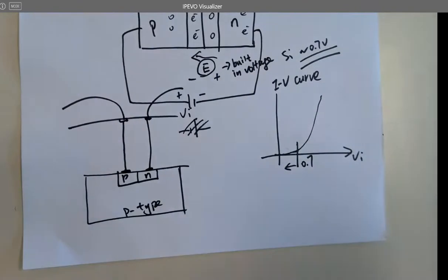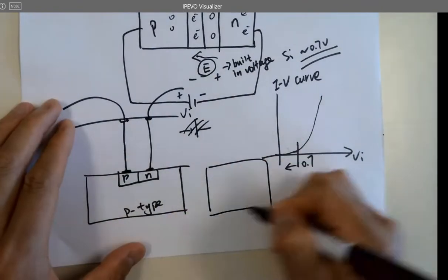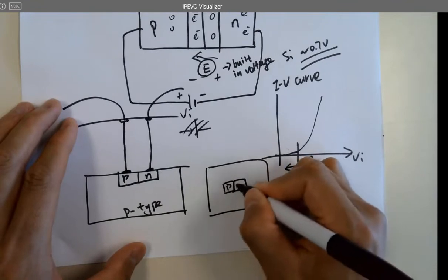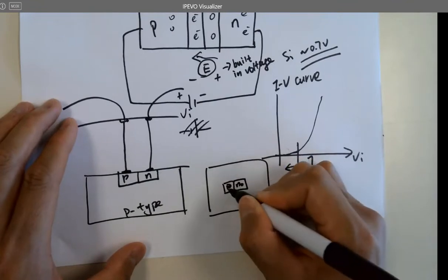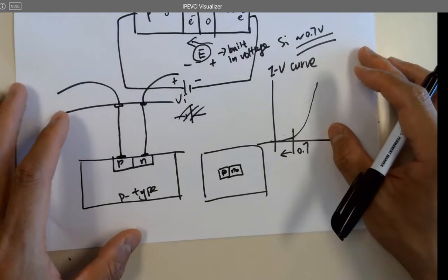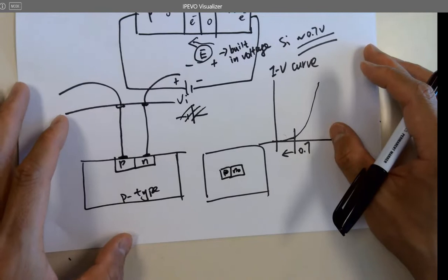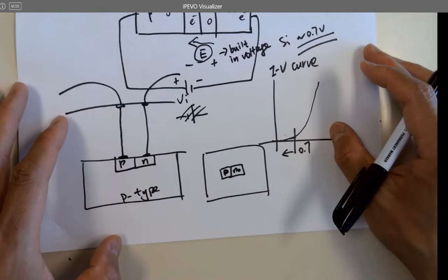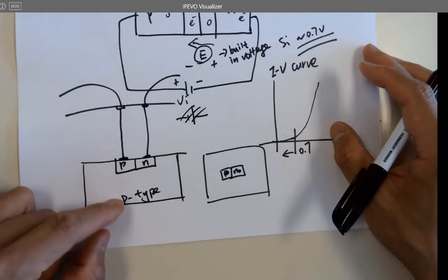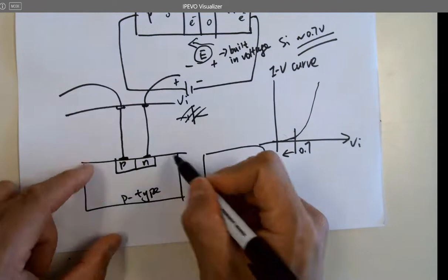It's a PN junction if you look from the top, right? Look from the top when you're doing the layout, you just put a P material here, put an N material here, and then you've got two connectors, one from each side, and it's a PN junction. It's not the way we do it. Why is that? Because P-type is still touching P-type, so you still have a ton of holes, and all those electrons go to those holes instead of pushing over to the N. It's like the whole thing is a P.